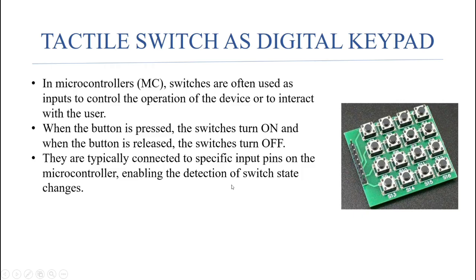And we use tactile switches and a digital keypad. In the digital keypad, here we can see the switches. These are called tactile switches. In a microcontroller, switches are often used as input to control the operation and to interact with the user, which means when we press the tactile switch, it will give the information to the microcontroller to access this function.